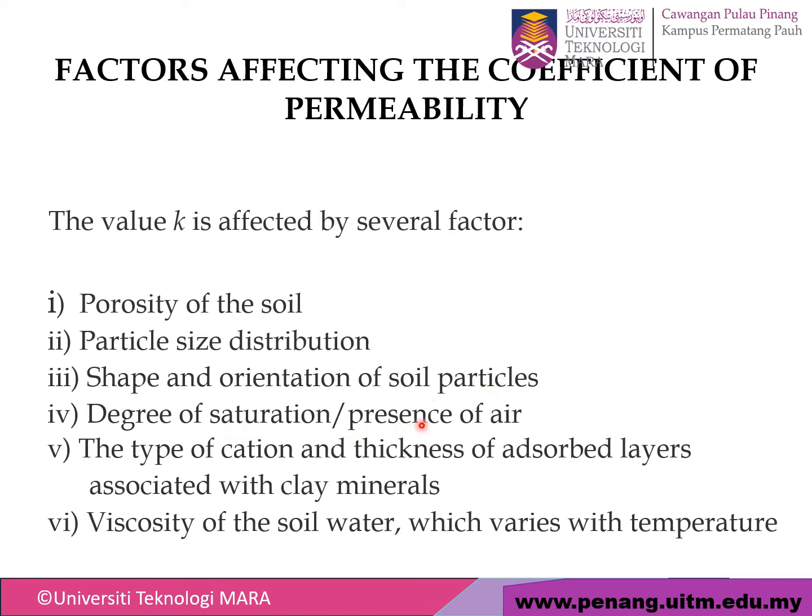Degree of saturation and presence of water, type of cation, and thickness of the adsorbed layer associated with the clay minerals. So that means if the thickness of the clay minerals layer is high, the K value is lower. Alright, viscosity of the water, which varies with the temperature. You may refer to the table, because different temperatures will give you different values of K.